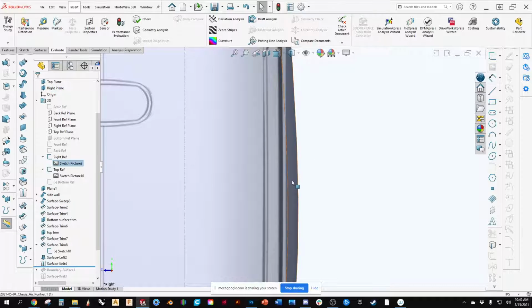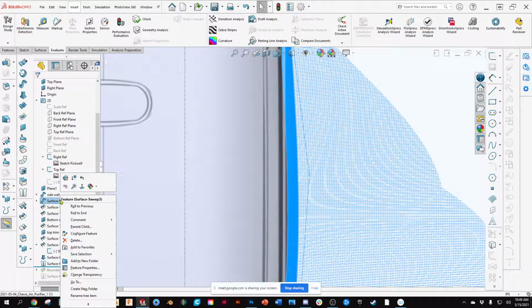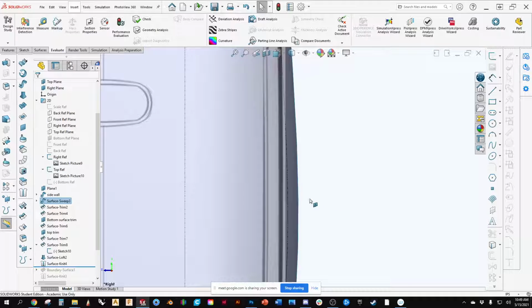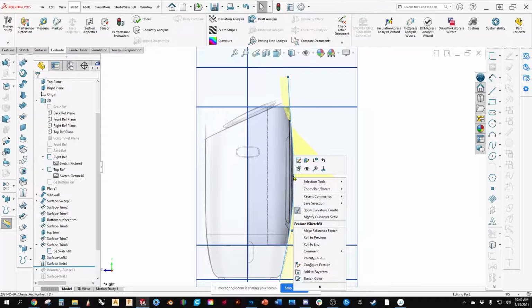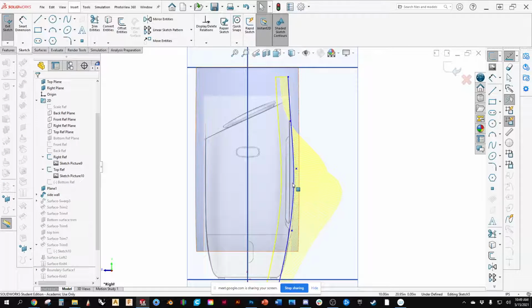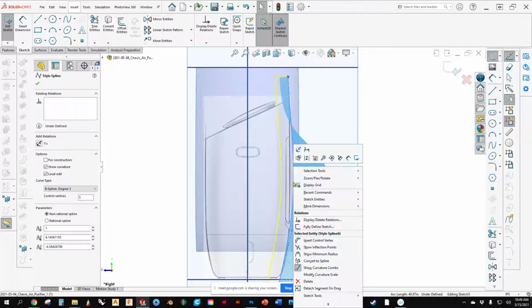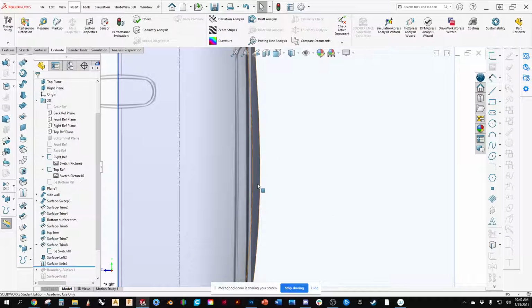Sketch mode to turn on curvature cones? I actually, let's turn this on and edit it. I have mesh preview curvature turned on in the surface. Nope. So I've got it turned on in the surface and I've got it turned on in here. So let's just do that. But you can see how my surface bulges out and it's not where it needs to be.